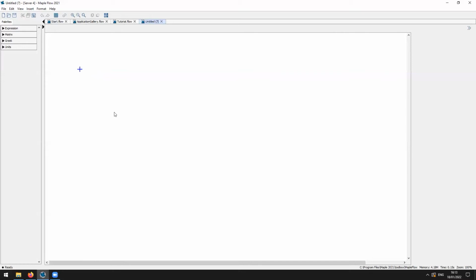Containers are created at the location of the grid cursor. So at this point, if I type in 1 + 1 followed by equals and enter, that creates a math container. I can move this grid cursor down and create another math container.